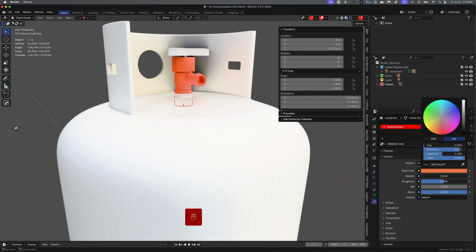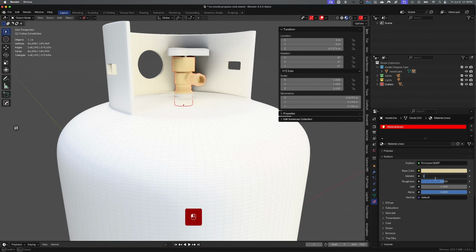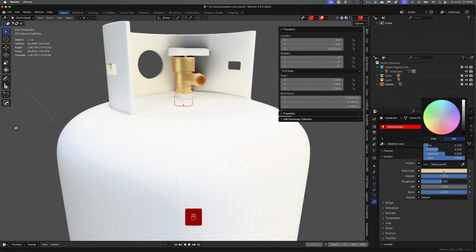Between the reds and the yellows, around orange, but a little bit more yellow. And then I need to lower the saturation and maybe play with the brightness, or lightness, just to get that hue right and get that tone right. And then I'm gonna crank the metallic value up to 100%, make it fully metallic. And then it's a matter of me playing with the roughness.